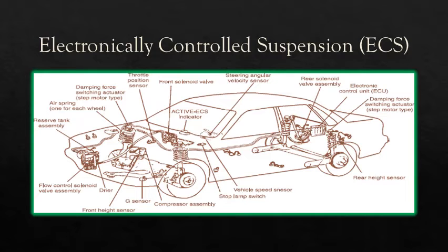One of the most uncomfortable side effects of a soft riding suspension system is pitch and bounce. The car either bounces vertically over sympathetic bumps or pitches back and forth over bumps which are asynchronous with the car suspension. By monitoring front and rear suspension, height relationship and suspension travel, the processor can instruct the offending wheel damper valve to change characteristics and eliminate the unwanted movements.